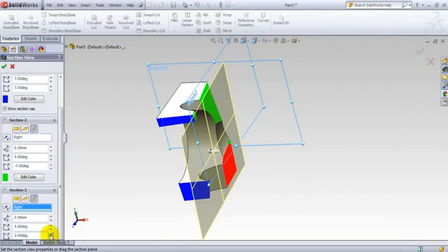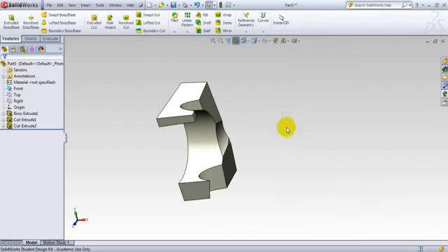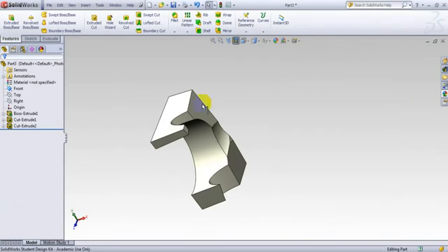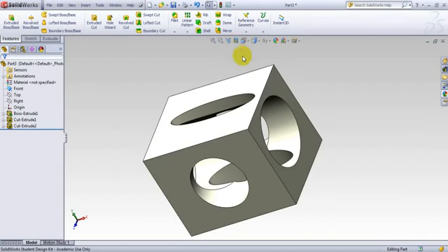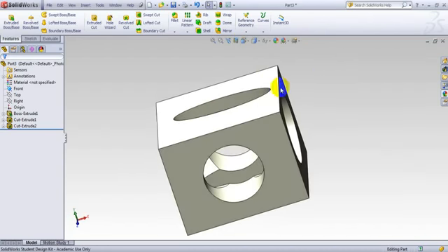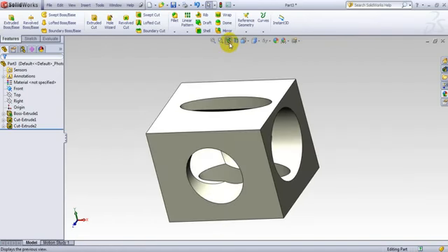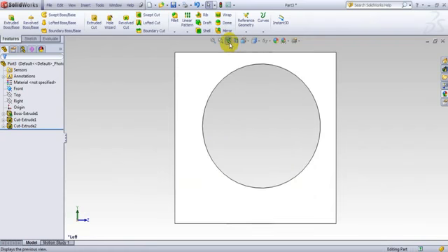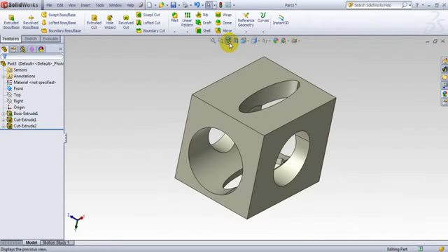So if you realize, it's a very handy feature, and you can see this is the remainder of what I sectioned. Sometimes it's very handy when you have a complex shape and you want to see how it's sectioned with one plane, and you can define the plane. And just double click on here, and it brings the previous menu. And this goes to all the previous menus here. You can check with this how many menus you can get.